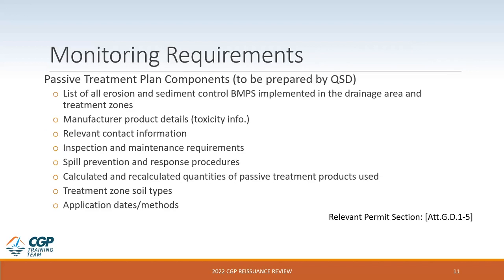So some monitoring requirements. There is the requirement to complete a passive treatment plan. And that document is to be prepared by the QSD for a particular construction site. And I have here a list of components included within that plan. And so we'd have a list of all the erosion and sediment control BMPs implemented within the drainage area. Again, the toxicity information from the manufacturer would be a critical component of that plan as well.